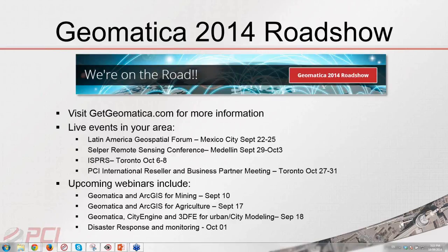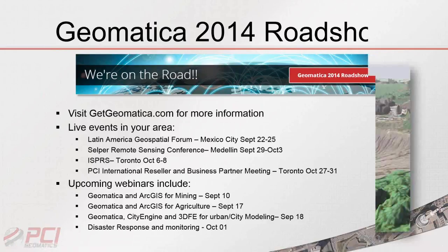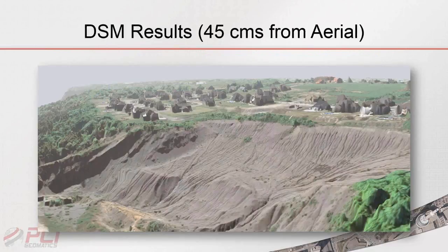But in those particularly challenging areas where you have slopes greater than 45%, we can actually employ a method using stabilizers. So if there's any areas where there's information between the trees, where we have a bit of an opening, we can apply a stabilizer there, and that will help make sure that when we do remove the trees we're not removing the natural terrain, or as much of it.